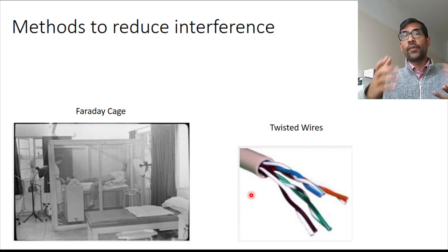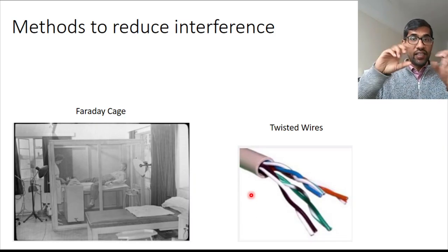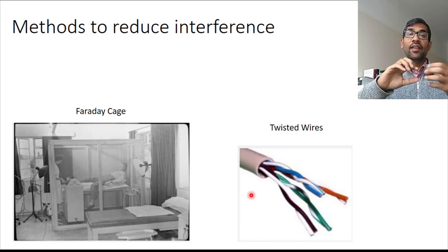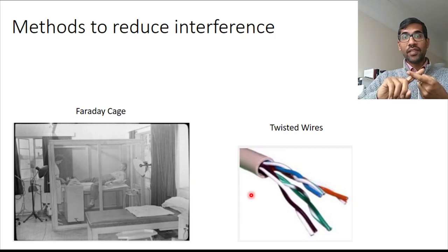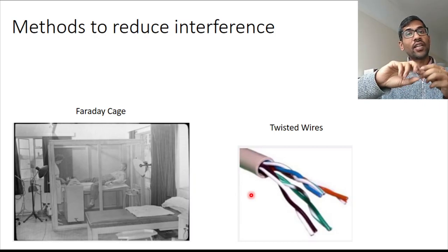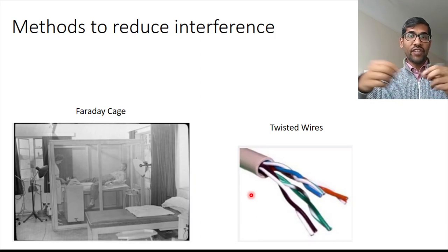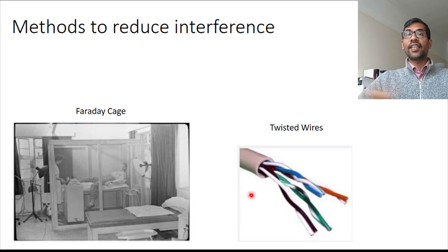Okay, so the first step in almost any biomedical measurement system is a difference amplifier or a differential signal. And if the same 50 hertz signal is imposed on both the wires, then that signal can be cancelled out. And the reason why the same signal is imposed is because it is twisted. So spatially, you cannot distinguish between the two wires. And therefore, you have the same 50 hertz signal on both of them, and they can be cancelled out.